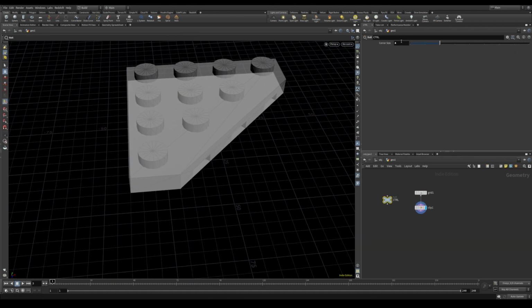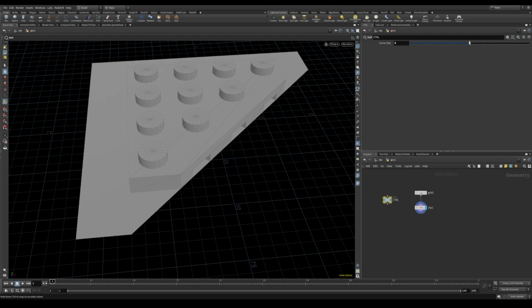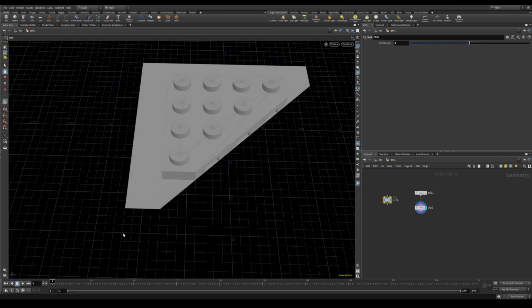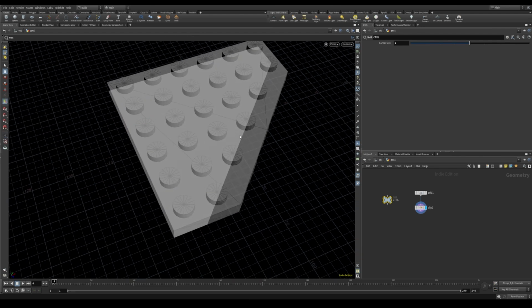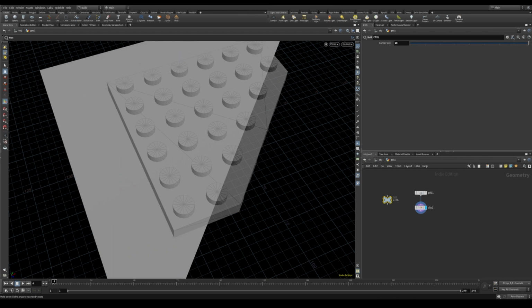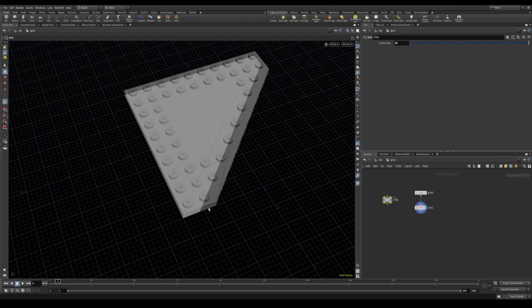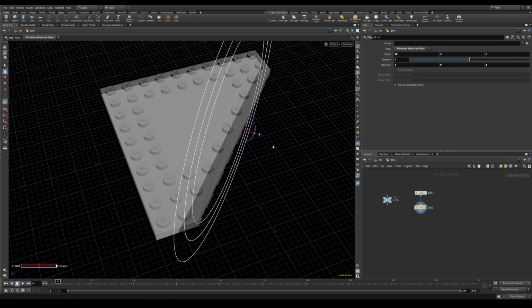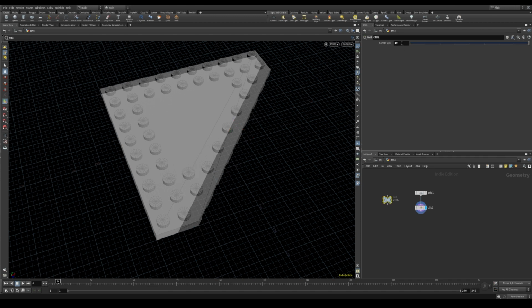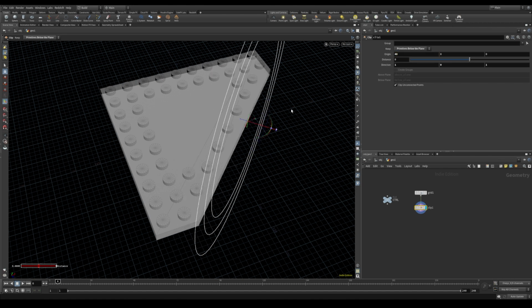So now we do have our cut, but we need to take care of the variation for the 6x6, which you can see as the cut more towards the x-axis, and also for the 10x10, because it does the same layout. And the way we are going to fix these variations is by using this origin x value within an if condition. So basically we are going to state that if this corner size is equal to 6 or 10, this value will be used, and otherwise the other value, 20, will be used.